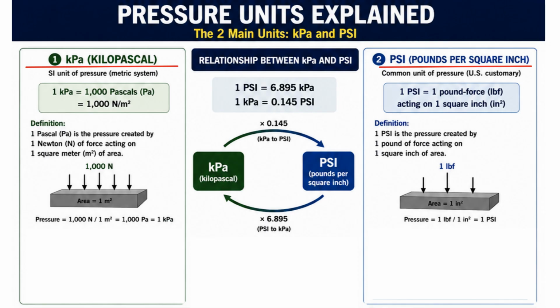In tyre engineering, kPa is generally preferred for calculations, while psi is often used during inflation and field maintenance. Whichever unit is used, always confirm the required tyre pressure from the vehicle or tyre manufacturer and avoid mixing the two units during calculations.